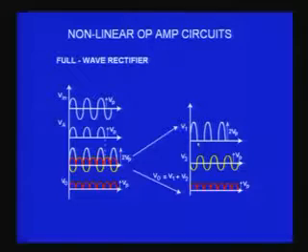If I come to the second half cycle, there is only 1 peak voltage in the upward direction, and there is nothing from the other input, and therefore when you sum them, you again get a peak voltage here in the same direction. So like that, for each half cycle you get only a net output peak voltage, and therefore when I monitor the output voltage of the summing amplifier, I get a full wave rectified signal.